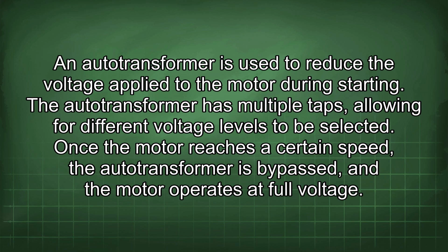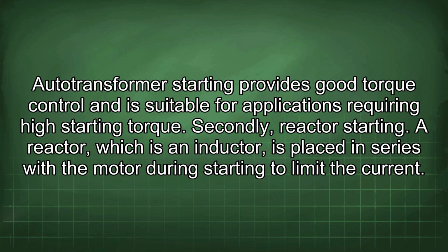Once the motor reaches a certain speed, the autotransformer is bypassed, and the motor operates at full voltage. Autotransformer starting provides good torque control and is suitable for applications requiring high starting torque.